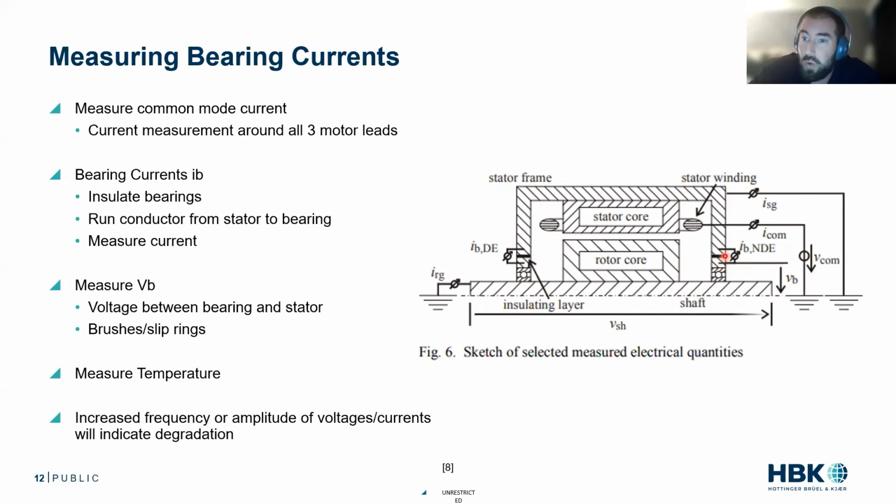What is more simple is you can measure the voltage difference. You can put a slip ring and a high impedance measurement between the stator and the rotor shaft. And granted, you're using a slip ring, so take that for what it is. But you can look at that charge and that voltage buildup and then watch it discharge. So you'll see voltage buildup, discharge, voltage buildup, discharge. That's probably the way most people are doing it.